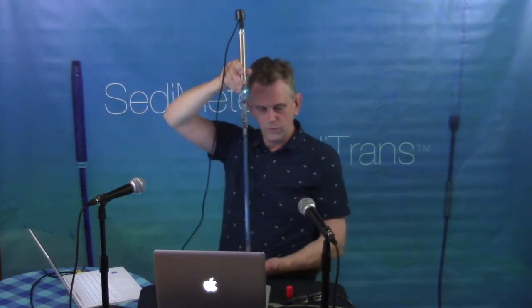If you put it on a platform, let's say a platform like this microphone, and it tilts over, the accelerometer will tell you it tilted over, and you know not to use those data. Furthermore, interestingly, the fact that we record the actual vibration, 30 measurements and not just one measurement, means that it's been possible in actual field applications to guess pretty well what has caused it to tip over.